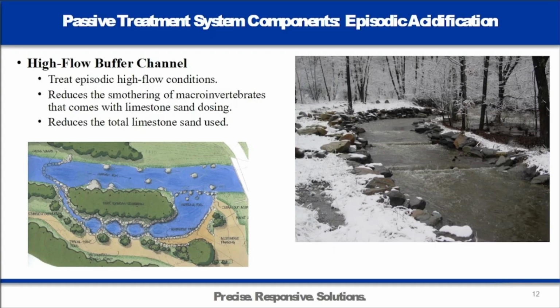One of the comments I had gotten from people on this type of design is that the contact time is not enough through the channel. What I have found in seeing these systems work is that you actually get more of a mechanical abrasion of the system that's releasing that in there. It's not so much the chemical dissolution, but more the mechanical breaking up of the fines and getting them within the watershed. And this is one that has been within the watershed since 2012, when it was installed.